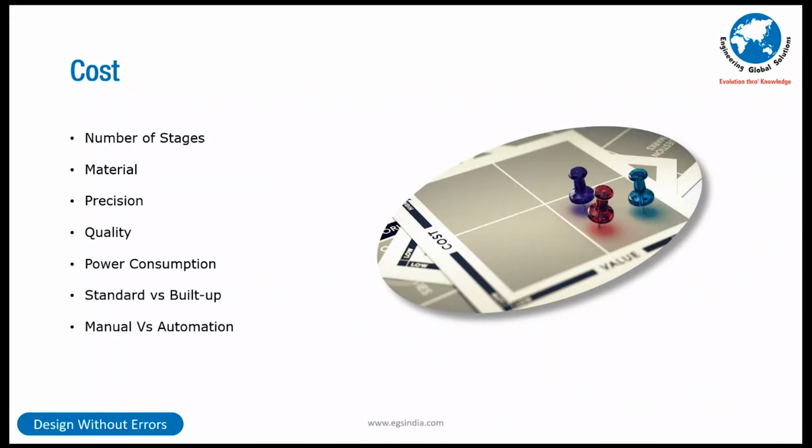The number of stages. For example, one of our customers is developing a sheet metal component in 3 stages. The standard material thickness is 3.4 millimeters, let us say. He goes through the 3-stage forming process and it comes down to 2.8 or 2.81. That's a significant reduction in thinning. As a result of which, what happens? Your durability takes a hit. So if you say 100,000 cycles, there's no way you can guarantee 100,000 cycles if you have taken 3.4 as the nominal in your design.